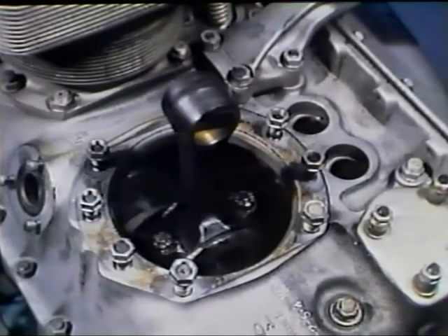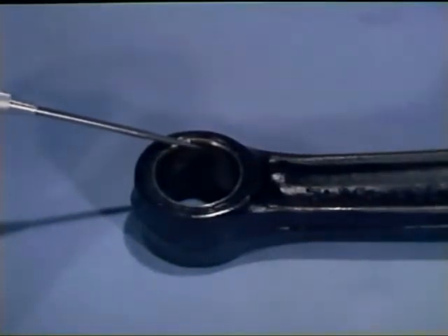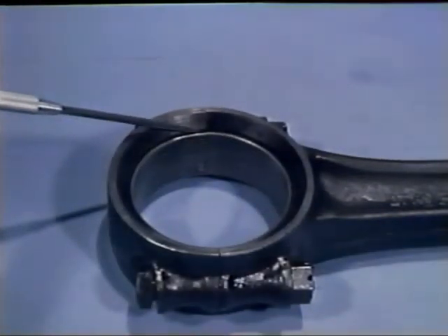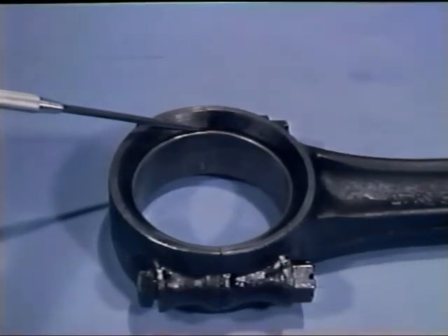Another component, the connecting rod, is forged of high-strength alloy steel. This rod changes the up and down motion of the piston into the rotating motion of the crankshaft. The smaller end of the connecting rod is fitted with a pressed-in-place bronze bushing. This bushing rides on the wrist pin in the piston. The larger end of this rod is fitted with a removable cap and a two-piece bearing insert. This allows the rod to ride on the polished journal of the crankshaft.